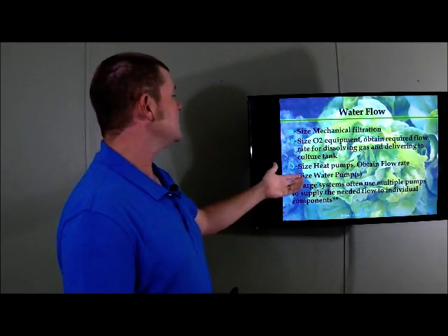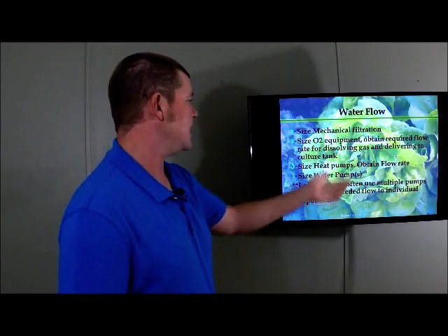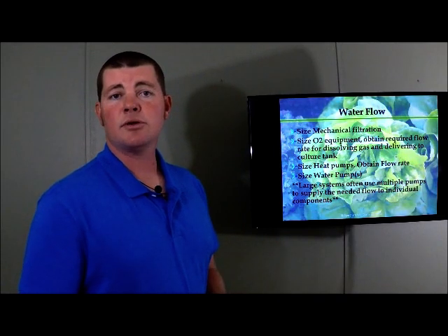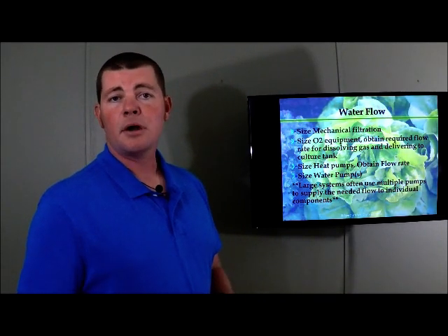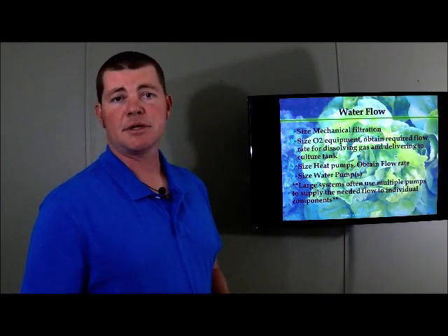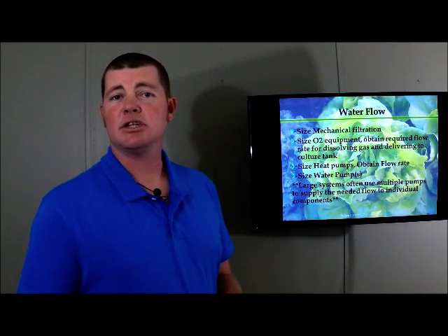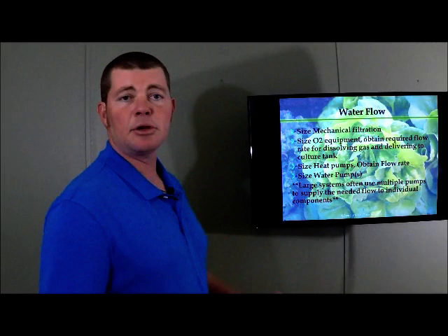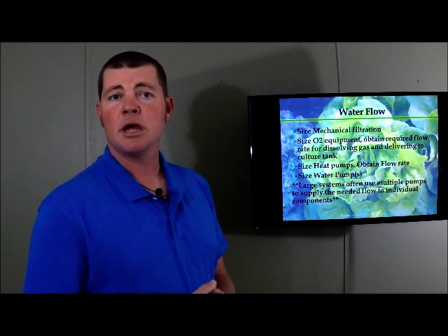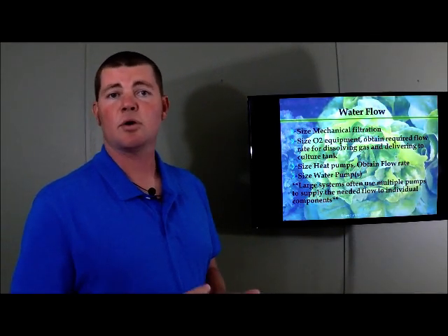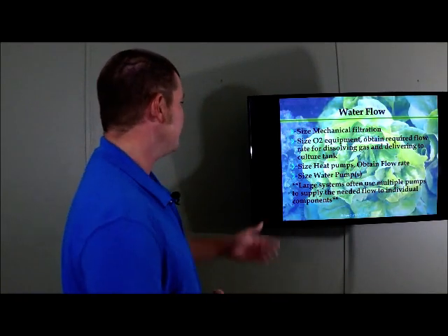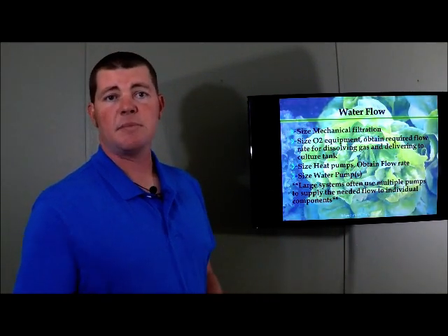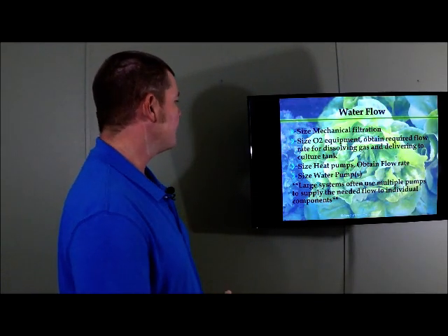We have to size our heat pumps to obtain a flow rate for that. So a heat pump is what you use to either cool or heat the water in a recirculating aquaculture system. Think of it like air conditioning, central air and heat for your house. Very similar, but the coils are submerged and the water flows by those coils and absorbs the energy. We need to size the water pumps for the total flow that we just mentioned in the slides before.